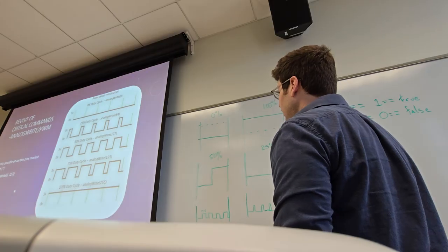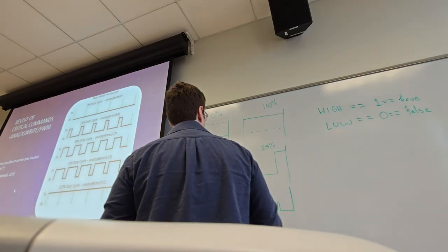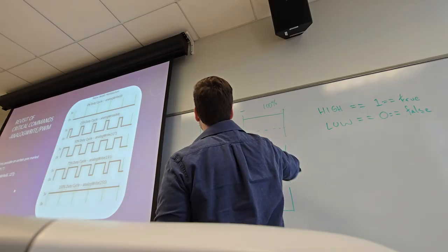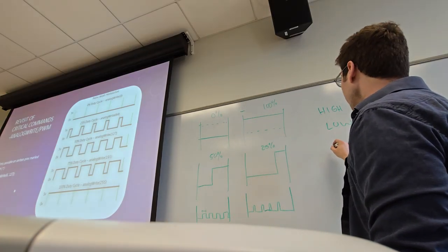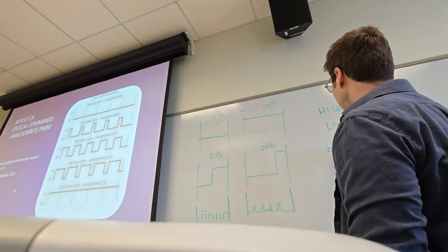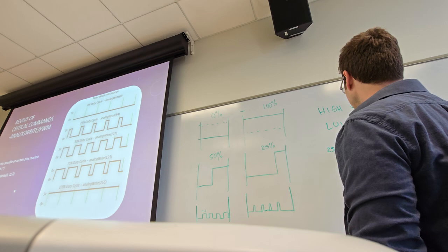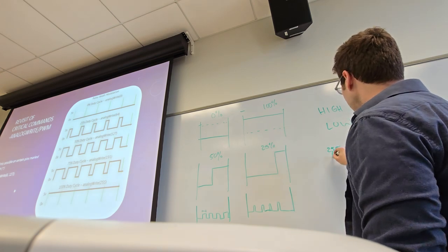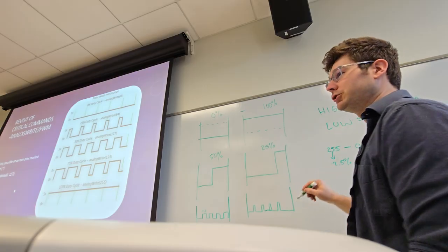So when we say a PWM signal of some duty cycle, we're just talking about between 0 and 100%. But remember, we scale it differently. There's 255 different chunks of 0 to 100%, so each chunk will be a 2.5%-ish difference.